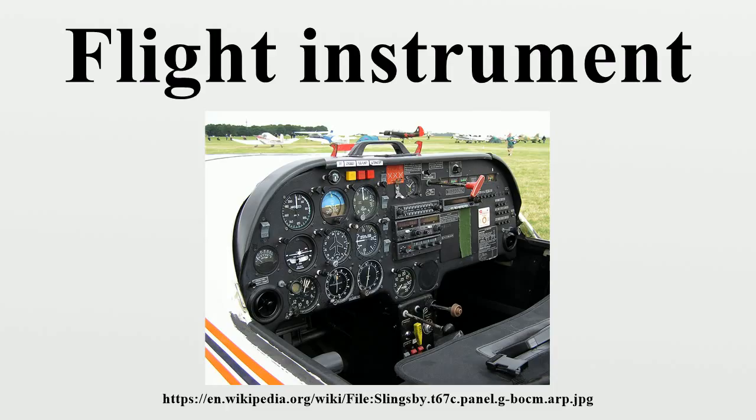It is needed to control the adjustment of the heading, to be the same as the heading of the landing runway. Indicated airspeed, or IAS, is the second most important instrument, and indicates the airspeed very accurately in the range of 45 to 250 knots. At higher altitude, a Mach meter is used instead, to prevent the aircraft from overspeed. An instrument called True Airspeed, or TAS, exists on some aircraft. TAS shows airspeed in knots in the range from 200 knots and higher.